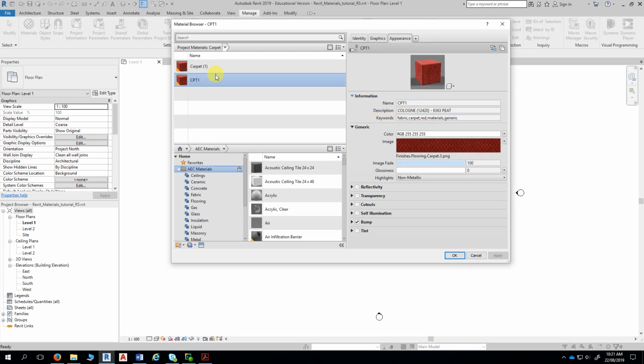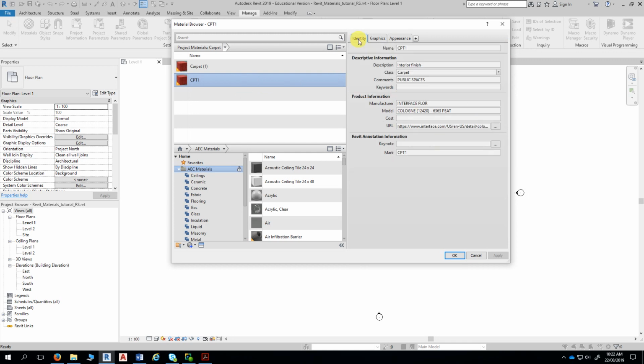So yeah, step 1 is duplicating the material. Step 2 really is duplicating the appearance asset. Okay, before you do anything else, so you know it's done. Because if you make changes and you don't duplicate, obviously it's difficult to know, if you're going to reverse those changes, what they were before you changed them. So, new material, new appearance asset, which is duplicated. Identity data has been filled in. Back to the appearance tab.